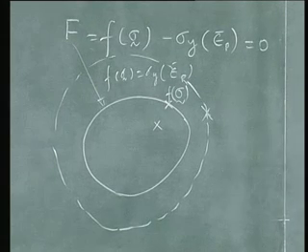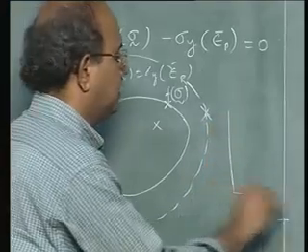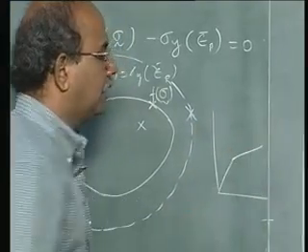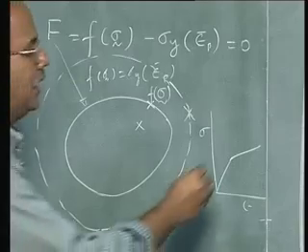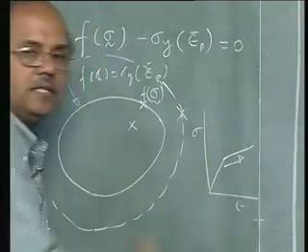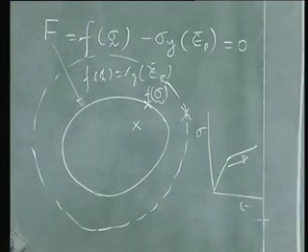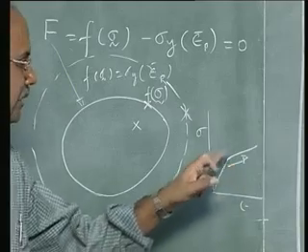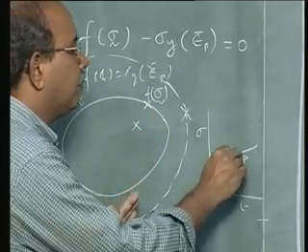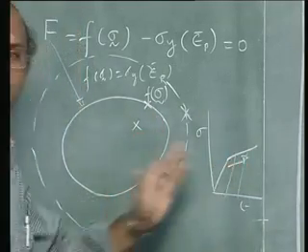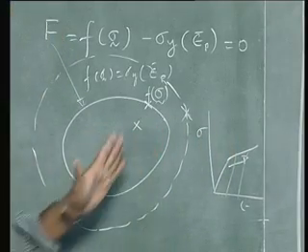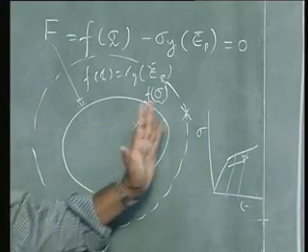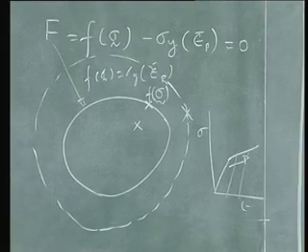What does it mean? It simply means in a one dimensional case that as I increase my stress, I will move in that line. Okay, I will follow that line, and that line is what would say the yield point keeps on increasing, and that's what it means in the 3D case, that there is an increase in the surface.